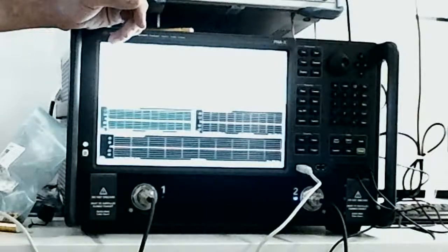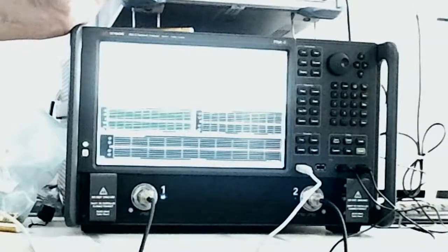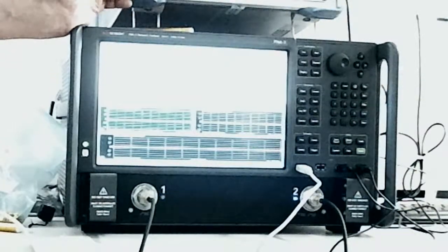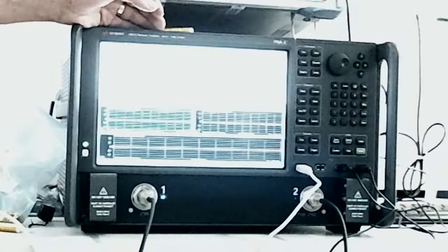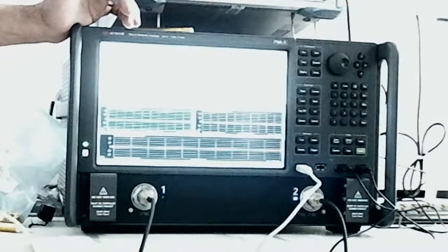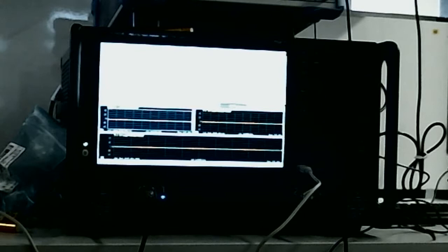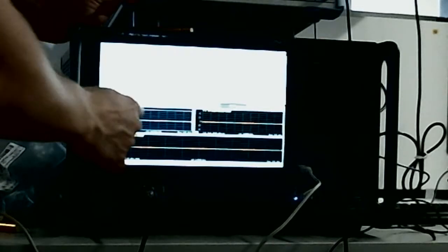This is usually if like you have a cable or like a fairly long kind of adapter. For this, you can just kind of like say, okay, depending again on frequency, right? So because you guys work at fairly low frequencies, I would not worry about this. But if you're saying, I have some customers that work at 40 gigahertz, something like this at 40 gigahertz makes a big difference, right? So I always recommend, to use that for 40 gigahertz, to use that de-embed adapter feature. For 1 gigahertz in this adapter, it's probably going to be 0.05 dB difference. So again, all depends on the accuracy you want to use.